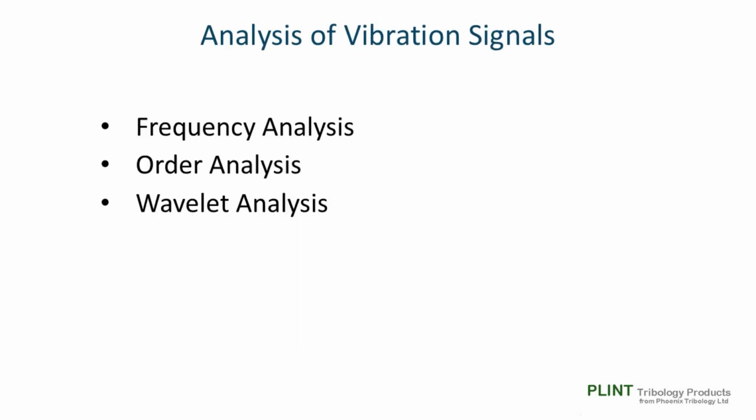For determining failure by macropitting, we need nothing more than an uncalibrated output from a basic vibration sensor or microphone. The output can be time-smoothed and damped. The magnitude of the signal is meaningless, and it is only used as a trigger or alarm device, not for making any analytical measurement. If we want to measure vibration in a meaningful way, we must use a properly calibrated accelerometer with high-speed data acquisition of the dynamic signal.